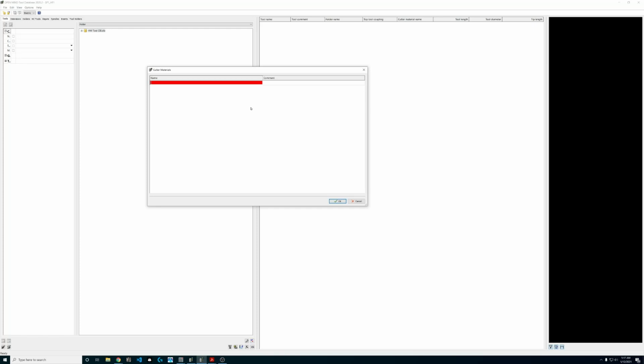We want to kind of identify these different series of tools or different groups of tools or list numbers of tools with a unique name, because we're going to take this name and we're going to apply all our feed and speed data to that name so that as we create tools inside of the database, we can say, hey, this tap is from this list number and this tap is from this list number, and one of them has a coating on it and one of them doesn't, so the surface footage is higher on this tap, and maybe this one's bottoming and this one isn't. The data that we decide to select for our tool is all going to come back and kind of be tied to this list.